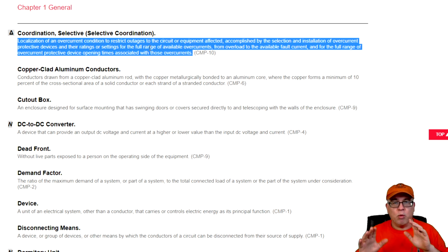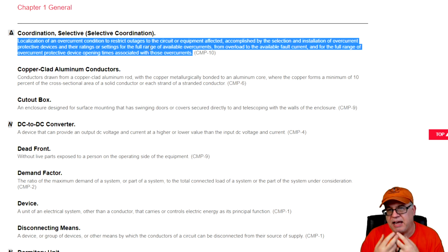A lot of words, and I took a break in there, and it might sound confusing. Again, a breaker or overcurrent device has to be able to operate within its range. That's why we buy it. That's why we're using it. We don't want to get slighted, but when we put it in the system, if something happens here at the end where a piece of equipment might be, I want the closest overcurrent protective device to operate and take care of that issue.